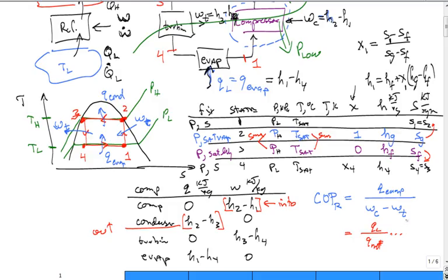In that case, the Clausius inequality is an equality when it's internally reversible. And then you can work out that the coefficient of performance for the Carnot refrigeration system comes in at TL divided by TH minus TL. How many people remember something like that? Everybody's going to raise their hand now. Yeah. Right? And we're never ashamed if we have to go back and review something in a previous chapter.